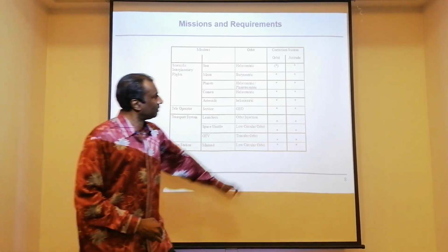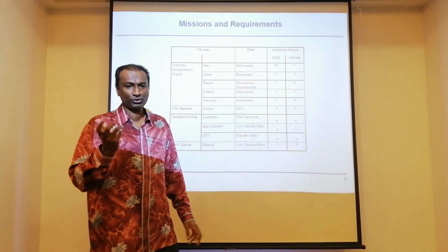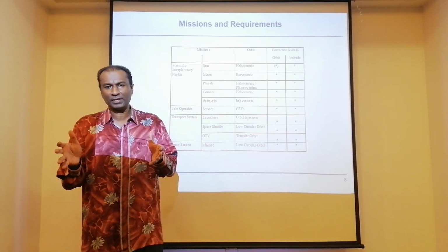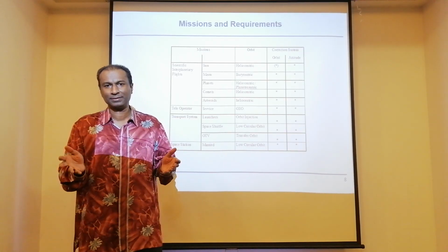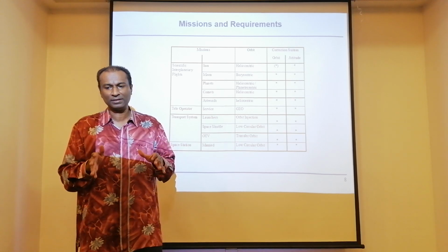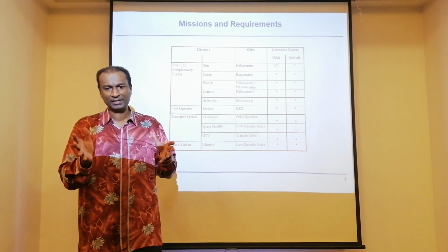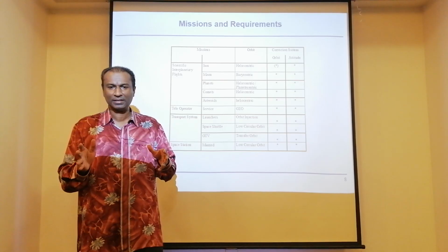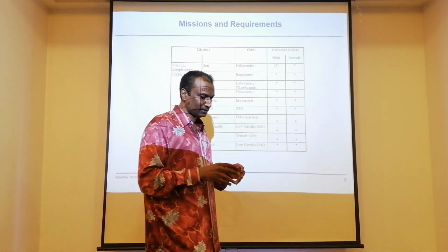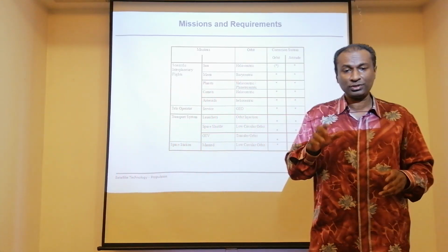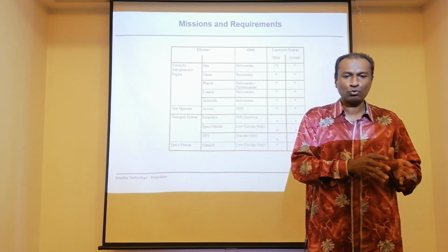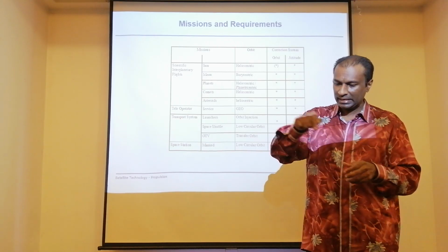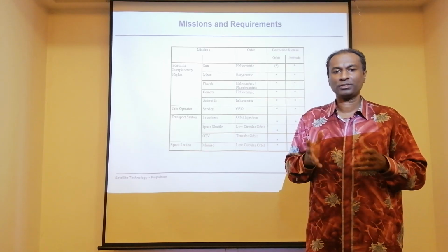But if you look at attitude motion, the rotational motion in any satellite, it is a must. You should have the attitude control system in a satellite. It is mandatory for any satellite. It could be low cost, etc., but rotational motion is mandatory. Translation motion, when operating in its orbit, is optional.